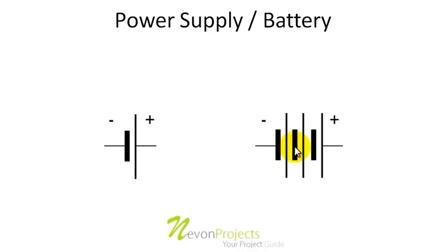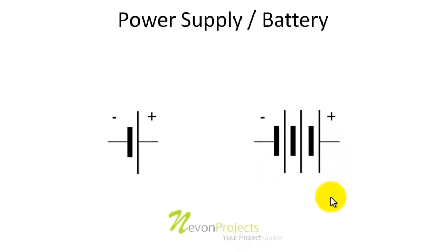Now a series connection here actually means the voltages are additive. That means if this single cell is, suppose, 5 volts and we have connected 3 of them in series, we can get 15 volts. So this is how the battery works.